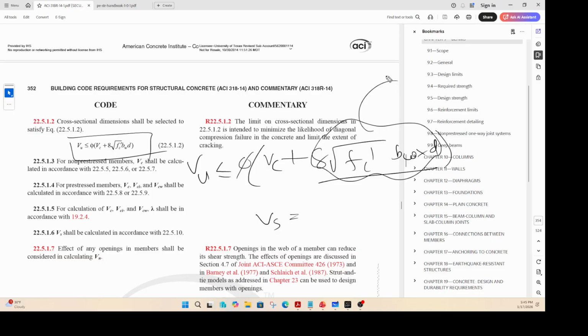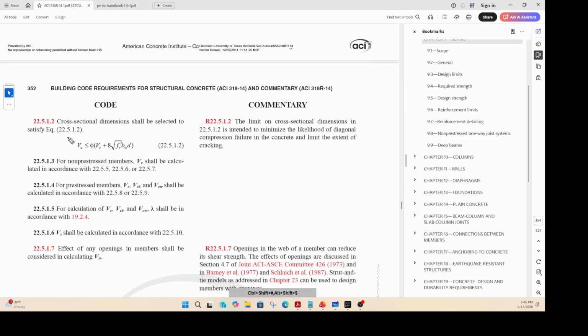Okay. So let's say the upper limit is 200 kips. Whereas the Vs that you calculated is only 160 kips, then you use 160 in your equation. Whereas if the Vs calculated is 210 kips, then you only use 200. Okay, that's the upper limit. So Vu has an upper limit. Sorry, Vs has an upper limit. So you need to realize and be careful with that particular thing.